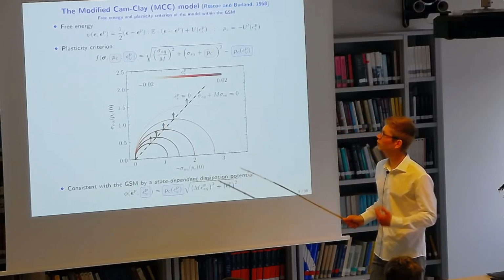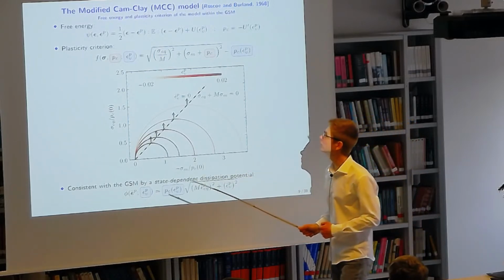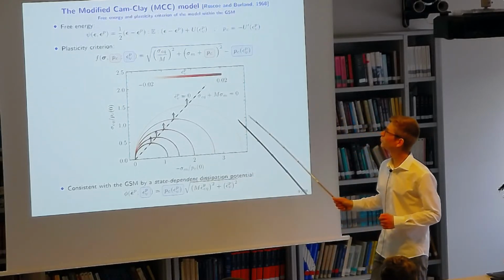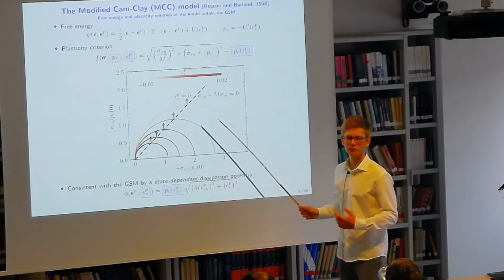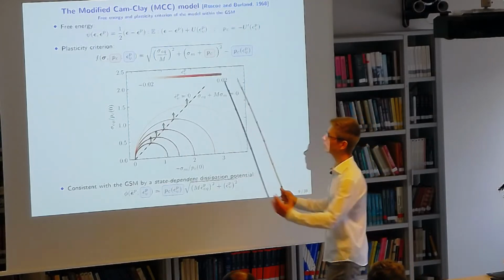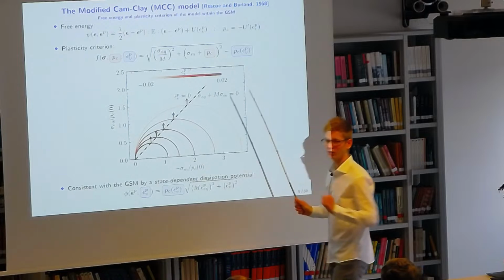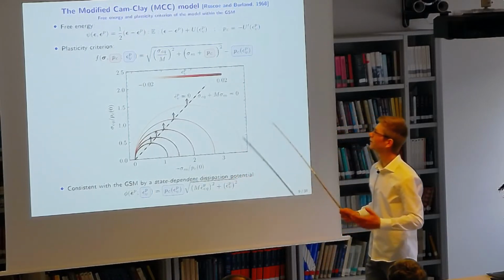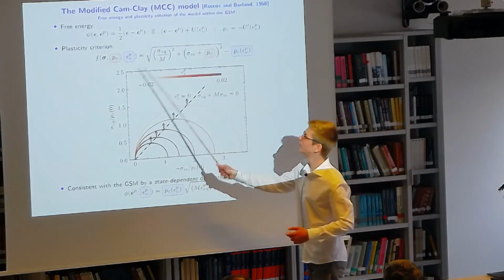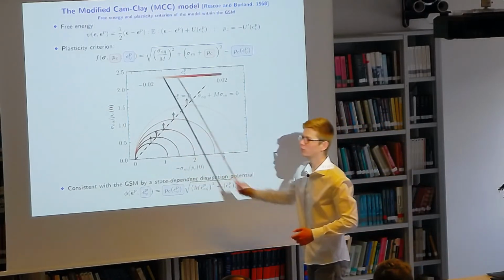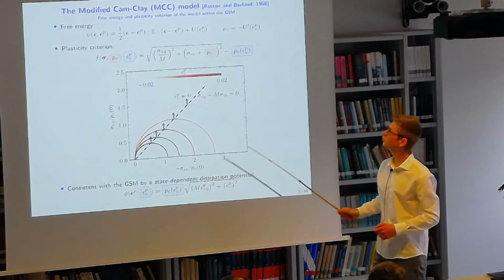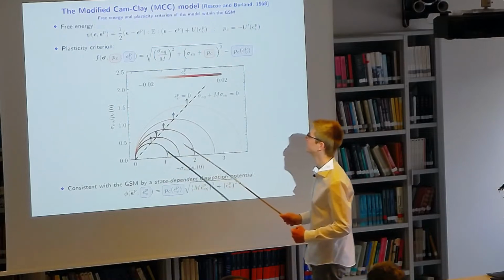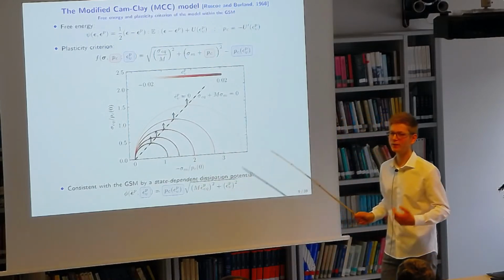And in this equation, you can observe two mechanisms of hardening. The first one comes from PC, the consolidation pressure, which acts like a back stress, which therefore is going to predict a kinematic hardening along the hydrostatic axis. Next, you can also observe the state dependency of the plasticity criterion by the volumetric part of the plastic strain. It's going to be involved in the evolution of the radius of the domain of reversibility. So this predicts isotropic hardening.